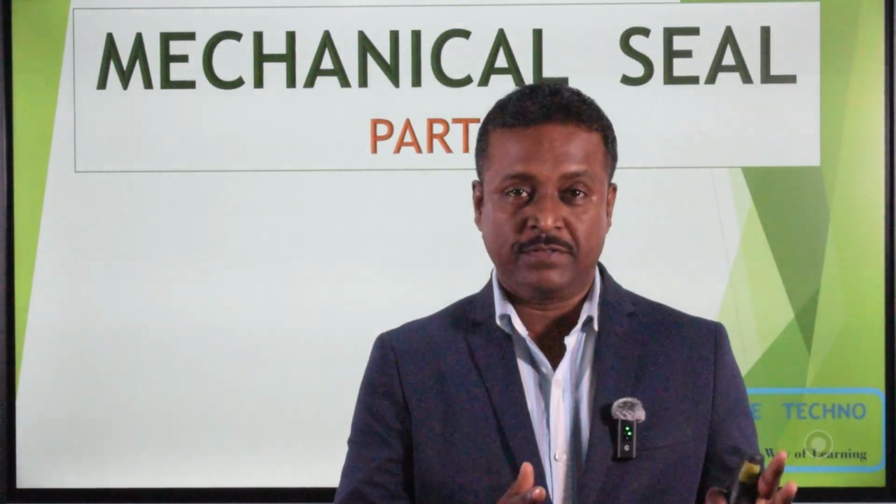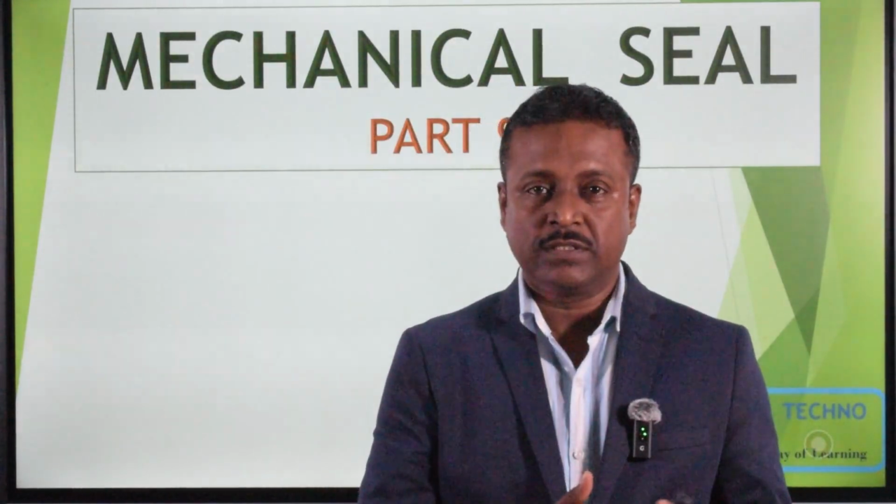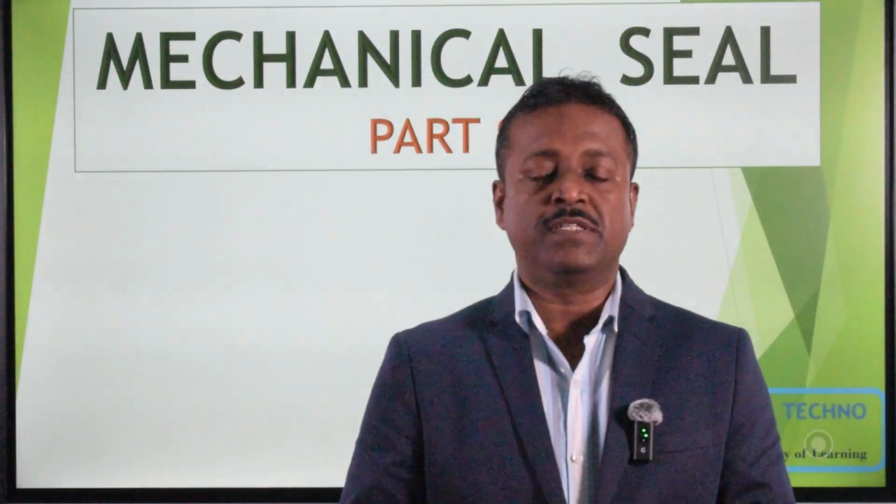Today we are going to discuss API seal flushing plan 53A. After the end of this video, you will understand what is mechanical seal flushing plan 53A, what are the main components, how it works, what are the advantages of seal flushing plan 53A, what are the main limitations of this particular plan, and a few basic interview questions.